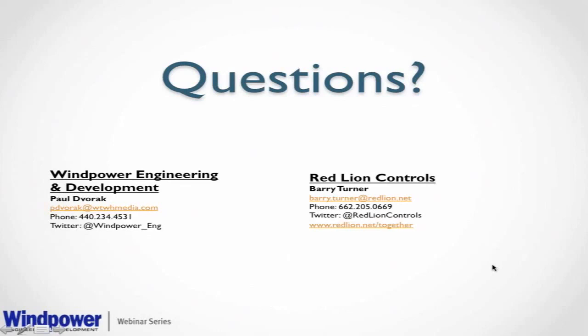That timeout could take a few seconds before you actually get a page can't be displayed. But in a control type network, you want that to happen immediately. So if the PLC or the drive were to stop communicating with whatever device it was communicating with, you need to know it right away. And so Ethernet/IP, for example, was built on top of Ethernet to add that deterministic nature to it.